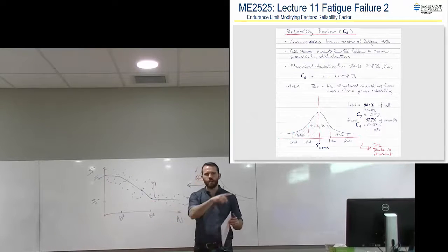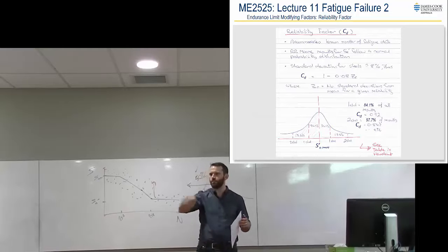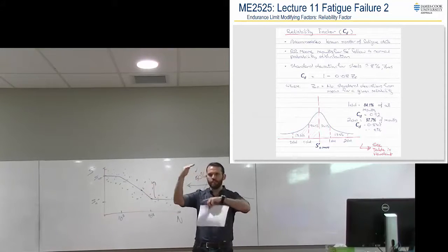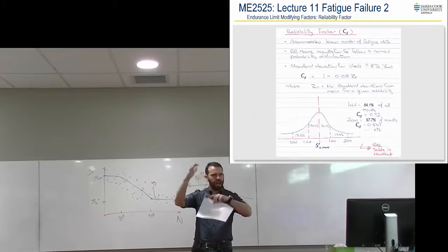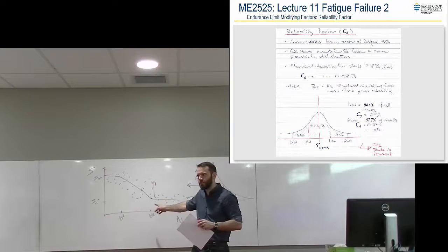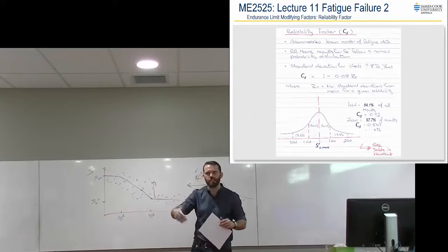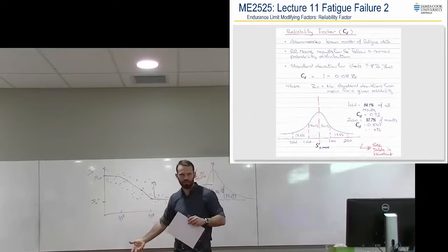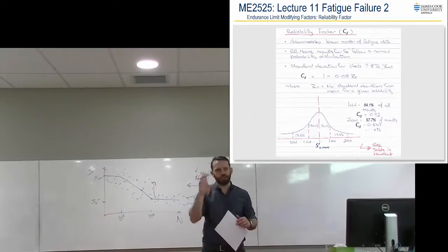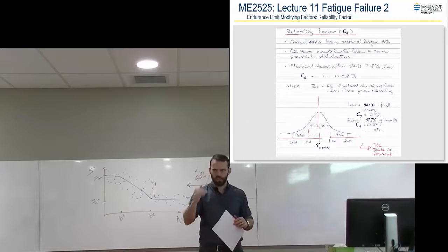So when you use our idealized thing for steel and compare that to what you get out of ANSYS for steel, they'll be different by a factor of 0.8 or 0.7 or something. It's because ANSYS is already doing this, which means when you do the ANSYS analysis, you don't need to do this again. So you need to understand this stuff, and when something looks wrong, you need to try and dig a bit deeper.